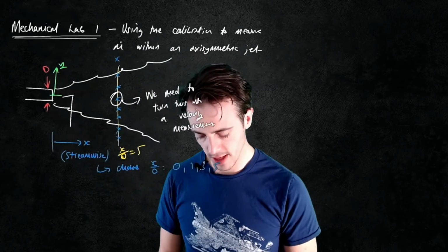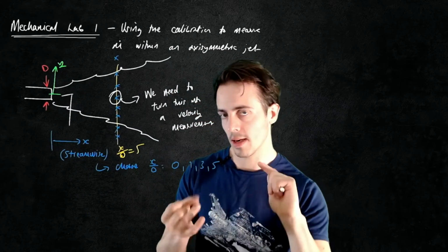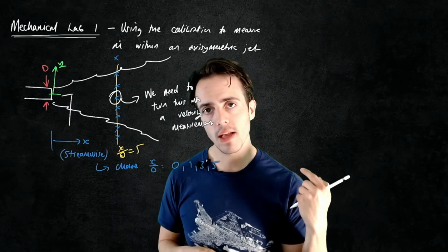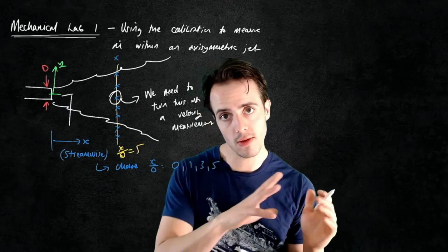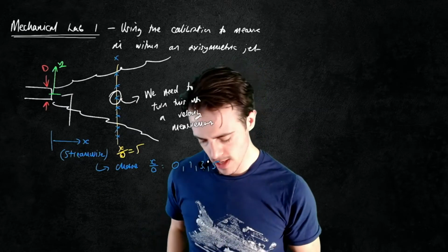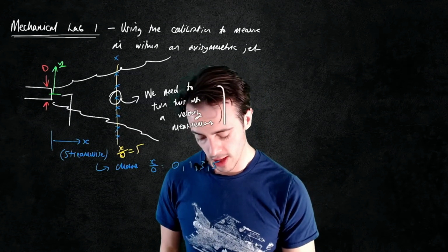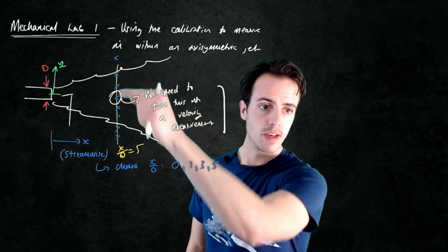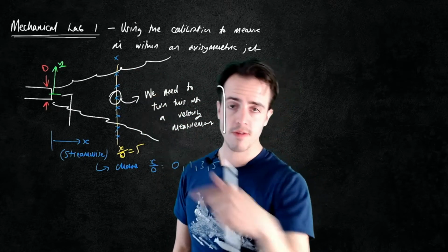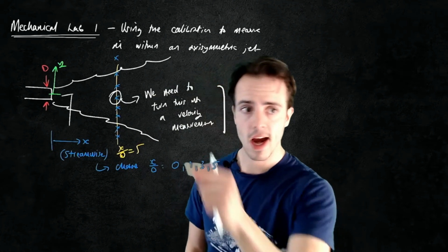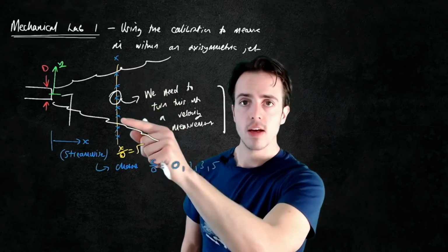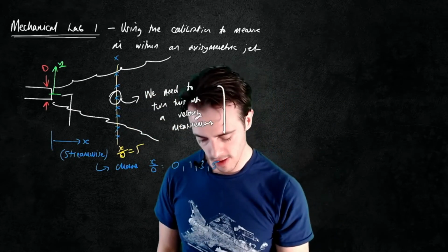So there's a couple of things that we need to do there. We've got a gain, so we need to turn it into a pressure, and then we need to use the Bernoulli equation to turn it into a velocity. Okay, so once we've got each of those, we then have a series of velocities, a velocity profile. We need to use the density of the air, and we then need to integrate along here to turn it into a mass flow.